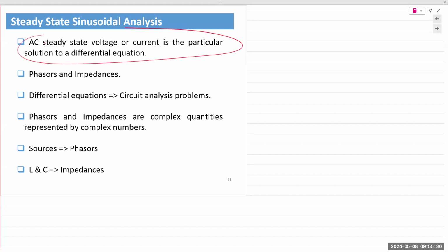that the AC steady state voltage or current, and again, we're only looking at steady state, not transients, can be easily represented as a vector. That's where the complex numbers come in. We use the imaginary numbers for mathematical representation, so the math is easier. Instead of performing derivation and integration, we can simply take our analysis techniques that we have learned in chapters 1 and 2 and apply them to solve for AC circuits. That's it, as easy as that.